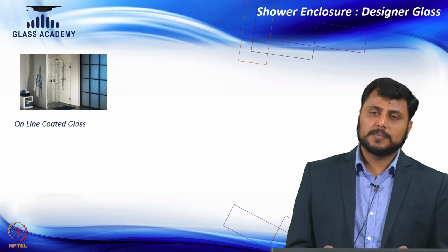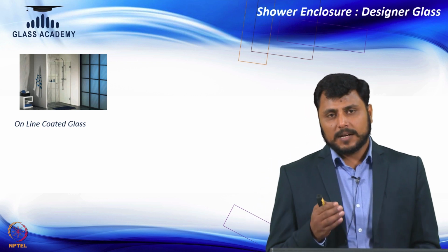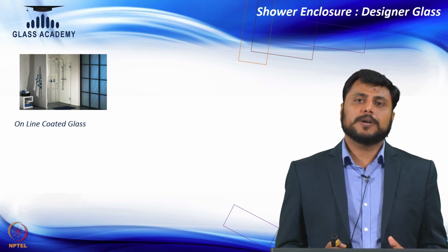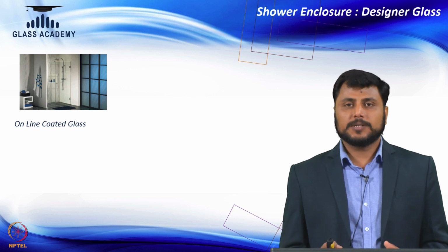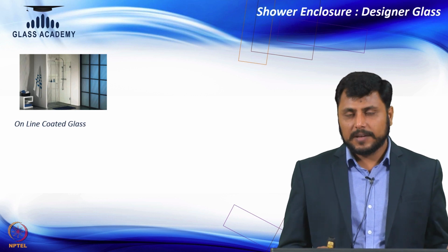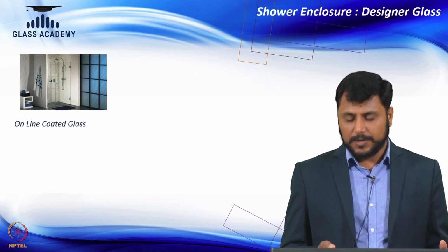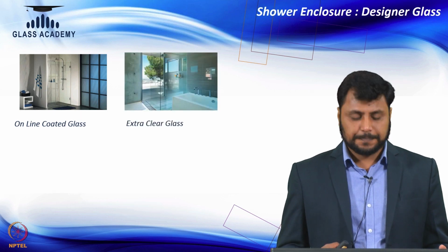As I said, there are some anti-limescale coatings available in market. So instead of that, there are some glasses which have got pre-coated. So coating is happening when the glass is being manufactured and being tempered. So at that time itself, the coating is being done. So that of course will have a longer life compared to the external normal coating. So that kind of glass can be used for this shower enclosure category.